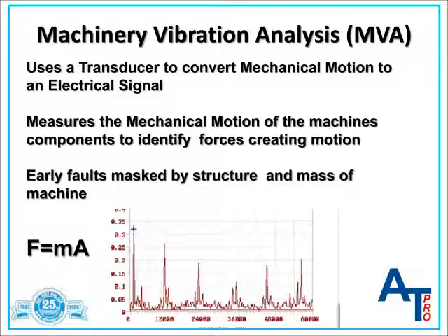Many developing faults may be buried in the background of the machine's normal operation, or the developing fault forces may be insufficient to move the bearing support or other parts of the machine that are being measured. The earlier the fault is detected, the more effective the program becomes.